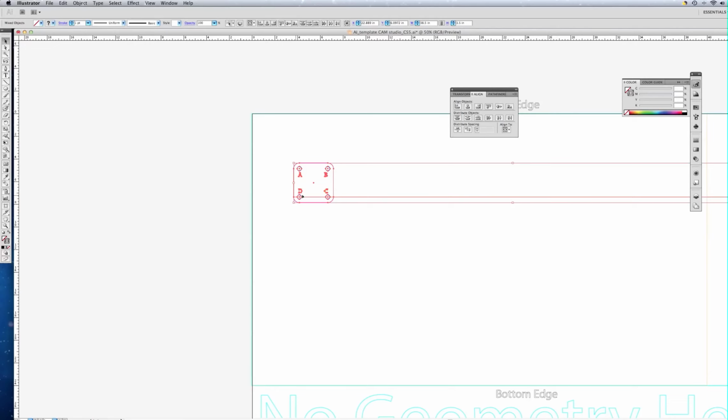So in order to have these spaced out equally on this line here, this reference line, we're going to need to horizontally distribute the objects. So we still want to be in our Align tool as we are here. However, in the command area, there's an Align to area here. If you don't have this shown, click in the top right, and this would say Show Options. If it says Hide Options, you have it open, but if it says Show Options, click that so you can get this menu that you see. So we have the menu up already.